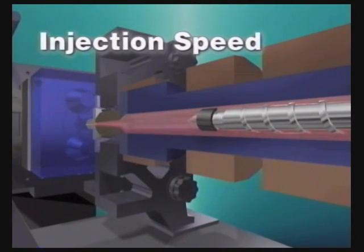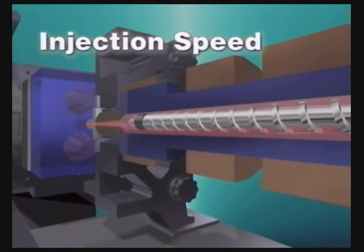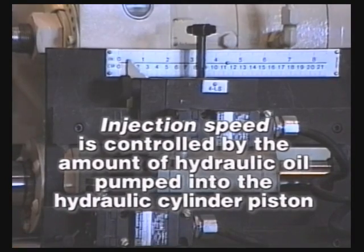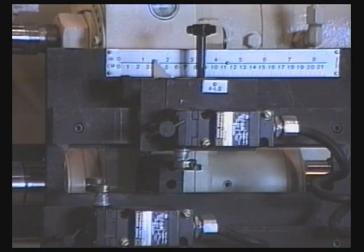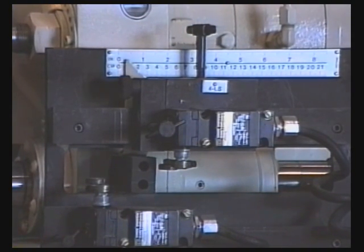Injection speed is a key processing parameter of the injection phase. Injection speed is controlled by the amount of hydraulic oil pumped into the hydraulic cylinder piston. Older machines have only a simple flow control valve to regulate the flow of hydraulic oil. Opening the valve allows more oil to enter the piston at a faster rate, and thus the plastic is injected faster.